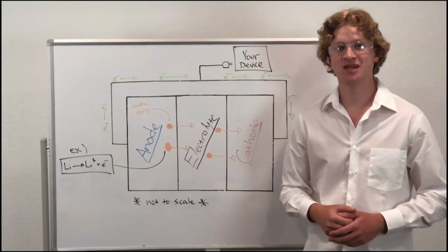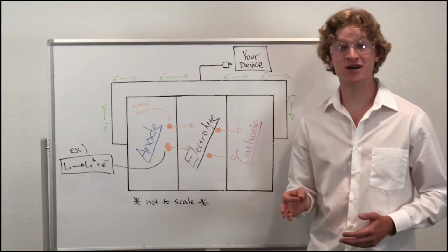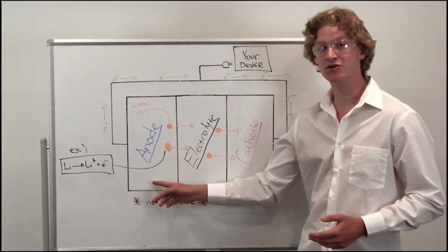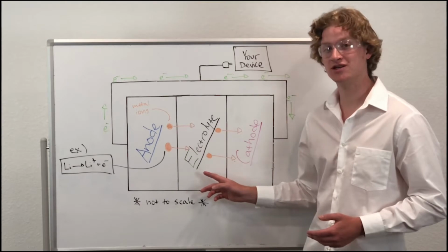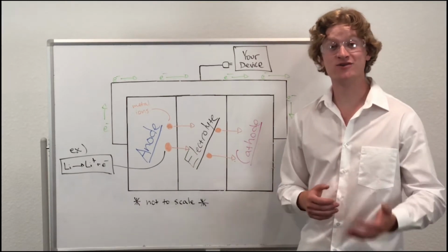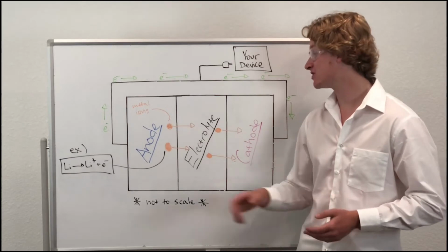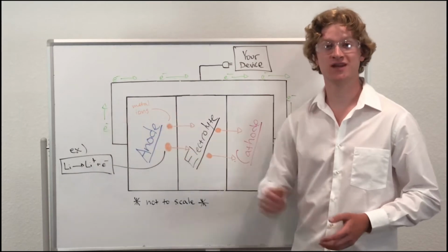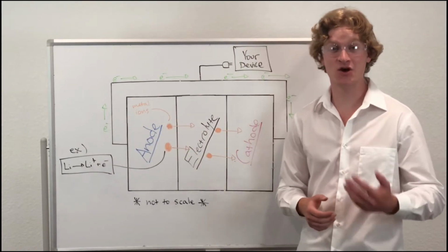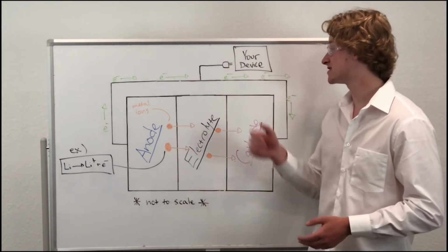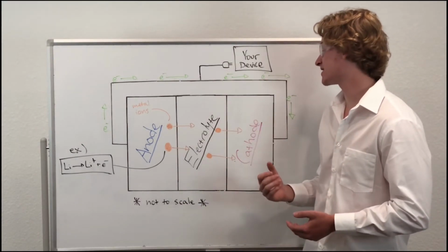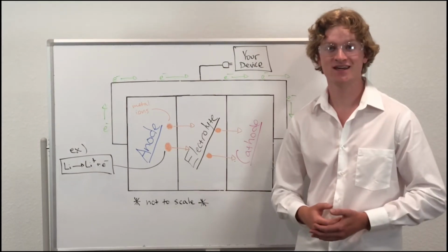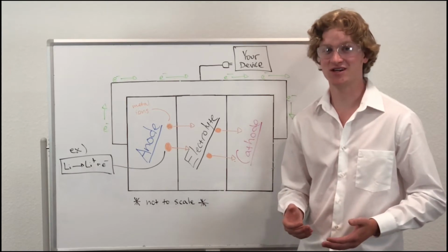Let's get started. Modern batteries are made up of 3 basic components: an electrically positive cathode, an electrically negative anode, and an ionically conductive medium in between called the electrolyte. When a battery is discharged, the anode undergoes a reaction in which metal ions are released through the electrolyte and electrons are released through an external circuit. This flow of electrons is referred to as a current, which allows us to power our devices. These electrons then recombine with their respective metal ions on the other side of the battery, and the process of discharge is complete. Yet, something is still missing in my explanation.